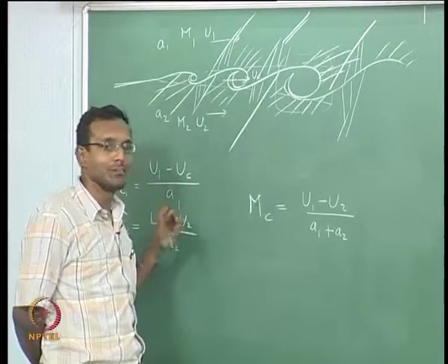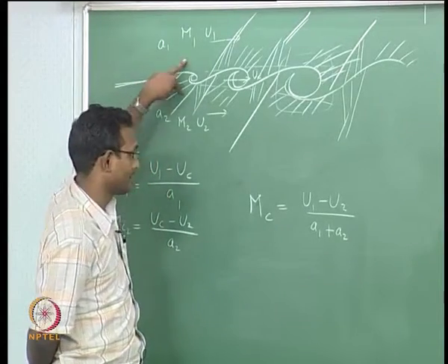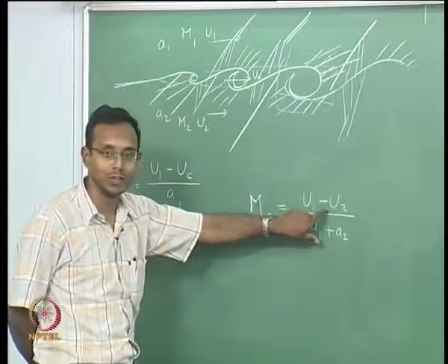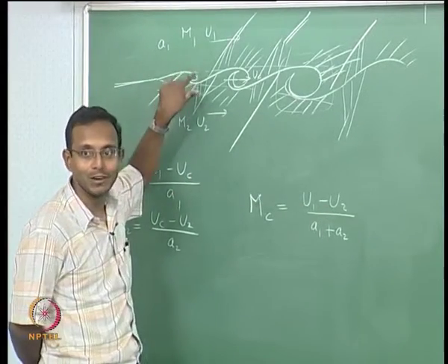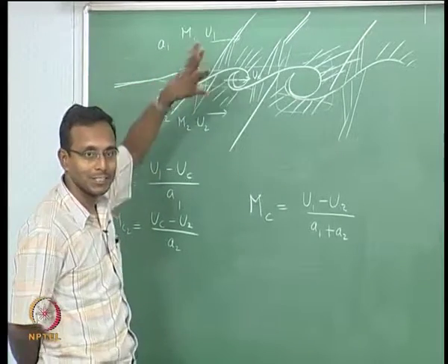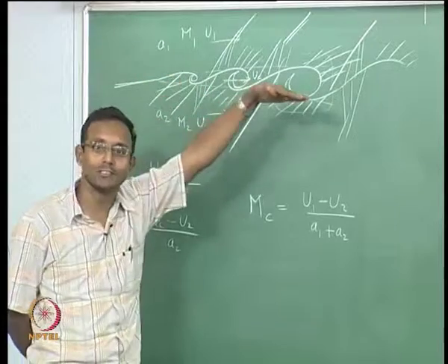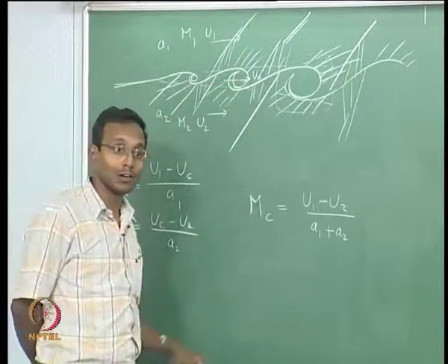If you want to think about it from a fluid mechanics point of view, the velocity difference is so high. When this number is high, u1 minus u2 is very high, which means my vorticity is very strong, and vortex breakdown occurs. It is no more just a 2D vortex; it breaks down and becomes streamwise vortices, and those streamwise vortices cause a lot more mixing.